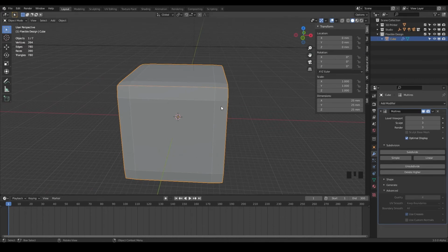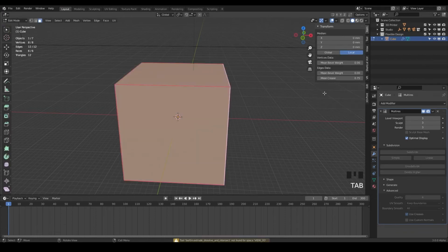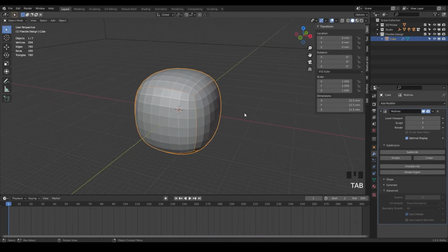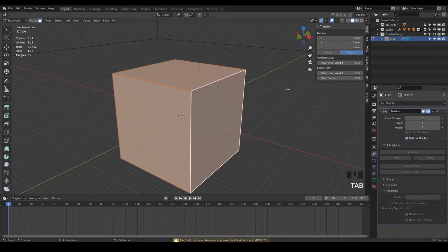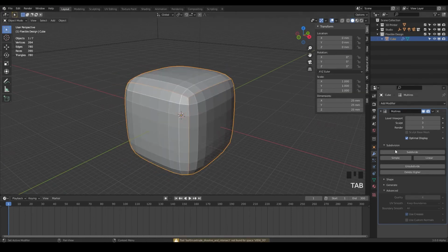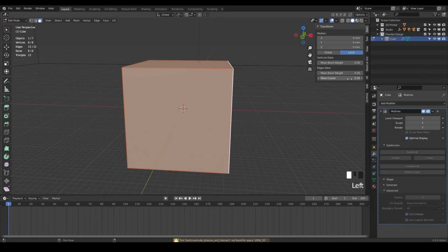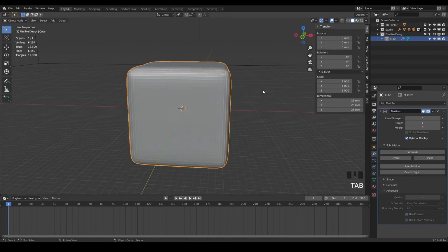Blender is taking into account the crease here. So if we crank that down a little bit, I'm just going to scroll it to the left, crank back over. Notice we can control how sharp our edges are with this tool. So I'm going to subdivide even more. And we're getting a really nice shape here just by adjusting these. So I'm going to do like 0.5, go back, and there we go.